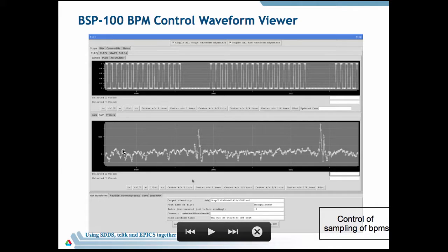And we have to be able to configure it. We have to be able to time these BPMs. So we have up here what the sample configuration would be. Here we have a 24 bunch pattern, but we only read, say, 20 bunches. There's a big gap here because the switches are slow and the data is invalid while we switch between planes. So this is how the BPMs are controlled.